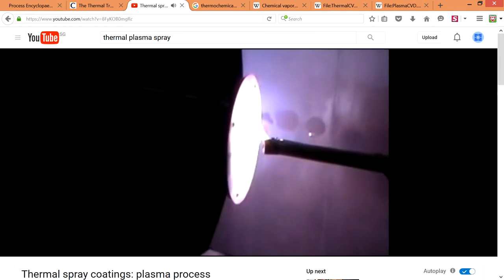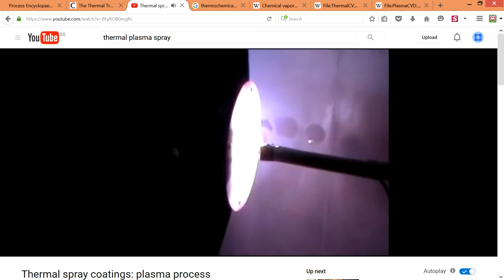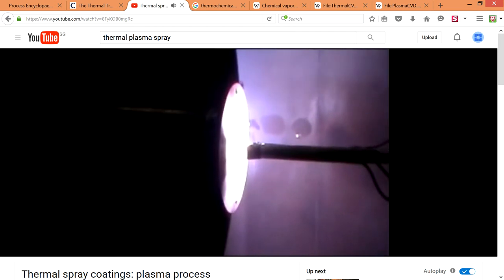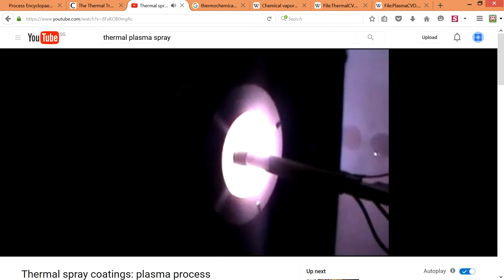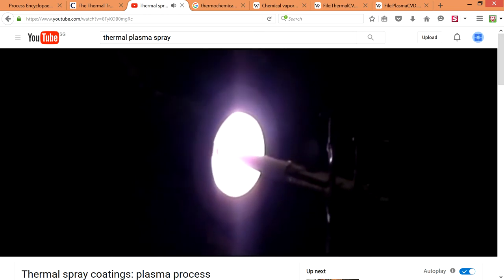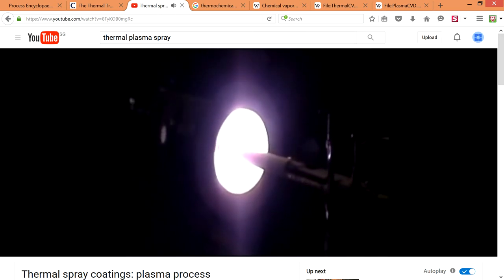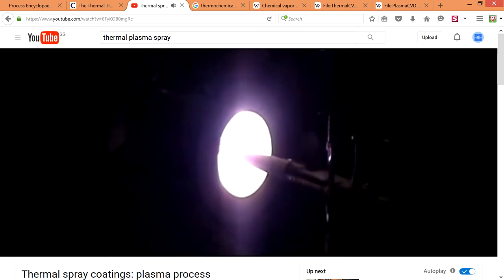The plasma coating process, as the name infers, utilizes ionized gases, bringing them to a state of dissociation. We then harness the resulting heat of this dissociation, or plasma, using a non-transferred arc method and feeding micron-grade coating stock into the ionized gas stream, melting and propelling the coating material to the workpiece. This intense temperature capability makes it particularly ideal for higher melting point materials such as ceramic coatings. It should be noted, though, that during this high-temperature coating process, the temperature of the component receiving the coating is maintained below 350 degrees Fahrenheit.